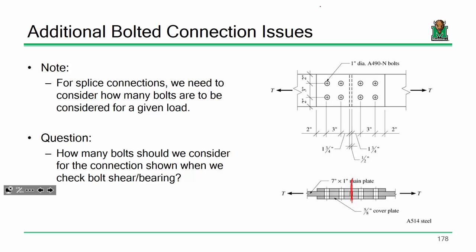That's a good point. I'm talking about gaps right here, like between the plates where water can get in, but it has a tough time getting out. Essentially I'm talking about capillary action, if you remember that from chemistry or fluids or whenever you talked about that. When the water gets in, it's got a tough time getting out. Water can easily get out of here, and when it gets windy and dries up, it's going to go away. I'm talking about the water that gets stuck. That's a good point.